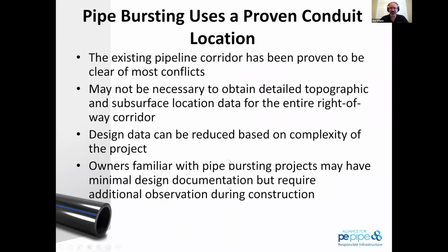So as I mentioned previously, we are using that proven conduit location. That is huge. And in some designs that I've done, since that location is proven, I actually use ArcGIS to essentially design the whole plan set, as opposed to a detailed topographic survey. From a municipal engineer standpoint, it saves significant schedule time, and it actually saves pretty significant cost.